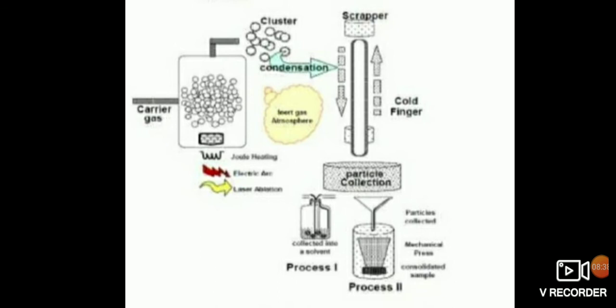With increasing gas pressure, vapor pressure and mass of the inert gas used, the average particle size of the nanoparticles increases. Log-normal size distributions have been found experimentally and have been explained theoretically by the growth mechanisms of the particles. Even in complex processes such as low pressure combustion flame synthesis, where a number of chemical reactions are involved, the size distributions are determined to be log-normal.